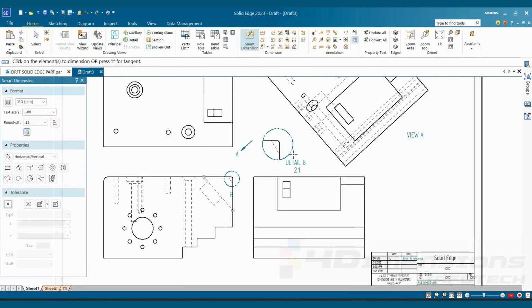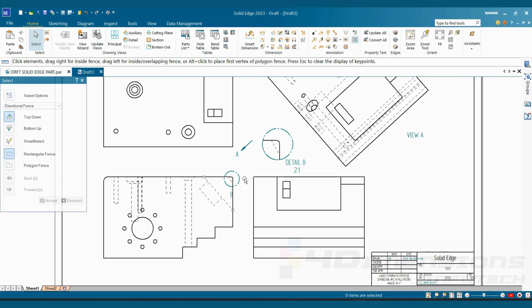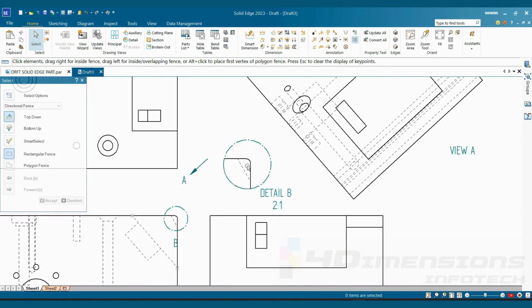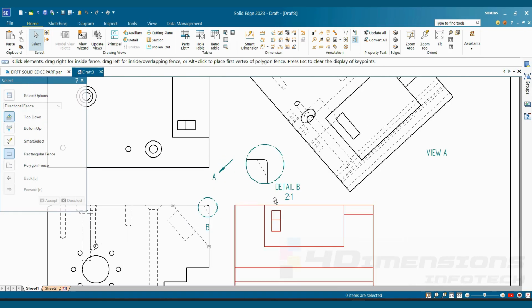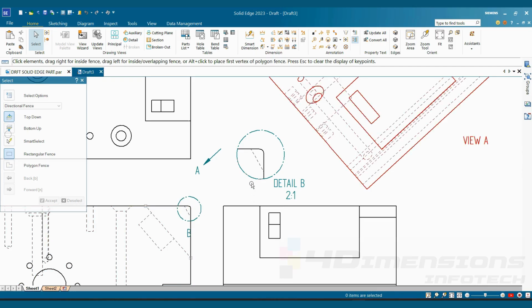Detail view means just to magnify that particular portion or the feature. It is not going to change the values of the feature here. Sometimes it is a misunderstanding that if this feature is being shown in 2:1, then the dimensions are also being doubled here. That is not the case. The dimensions will remain same. It is just for a particular viewer. This option is just to observe the view in a magnified condition without changing the value of that particular feature.